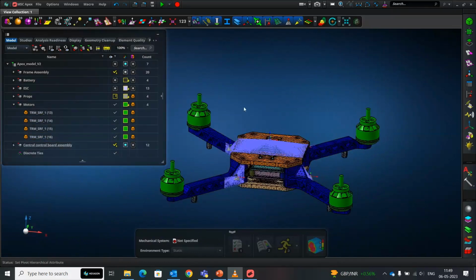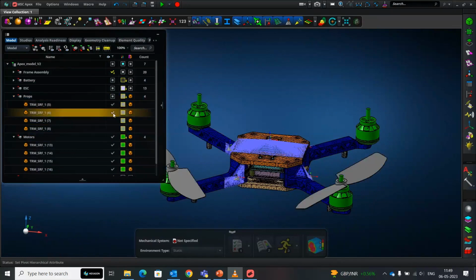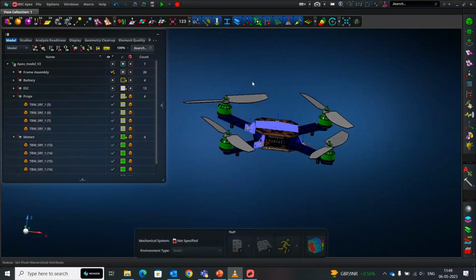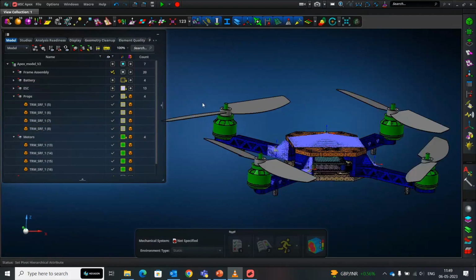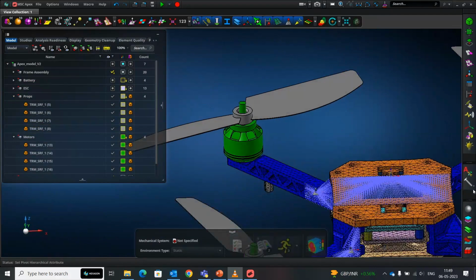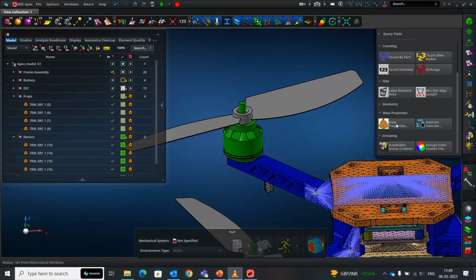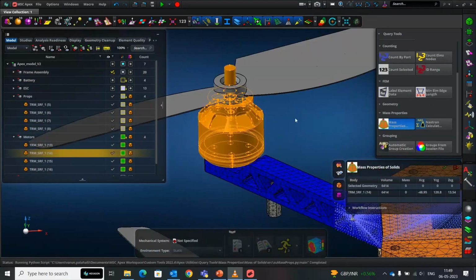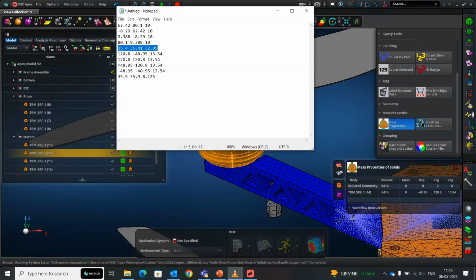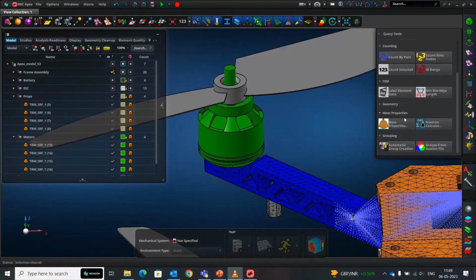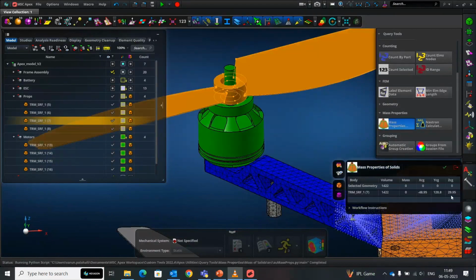So what I have done is I have taken the motors and I've also taken the propellers. The motors are of a particular mass, and the motors have a CG point, the corresponding CG of the motor. In addition to this, you also have the CG of the propeller itself. So what I've done is I've just used a simple weighted average method of getting the net resultant CG, something very standard, what you've already done in strength of materials or even mechanics in your initial first year courses.